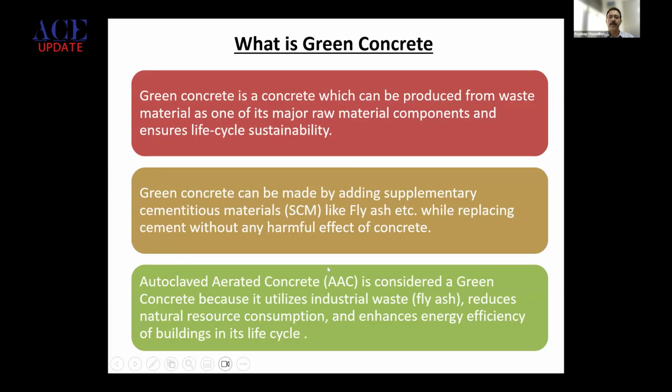Green concrete is also made from supplementary materials, like we're using fly ash here. That can be from other industrial waste, of course, because we extract from it the silica and the calcareous portion, the calcium siliceous factor. So we extract those components from fly ash. And autoclaved concrete is also green concrete because apart from utilizing fly ash, it also takes care of various aspects, like not using any topsoil or any kind of natural resources, and it also enhances energy efficiency